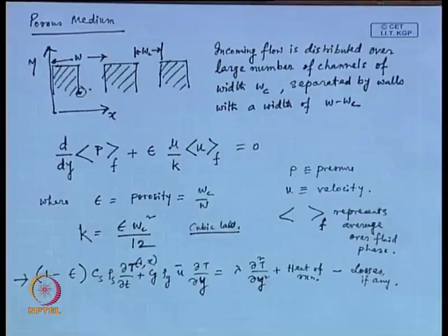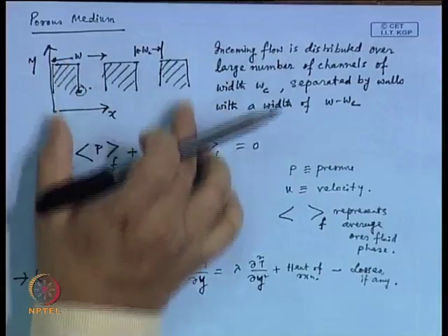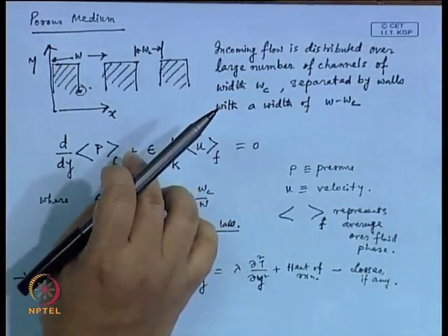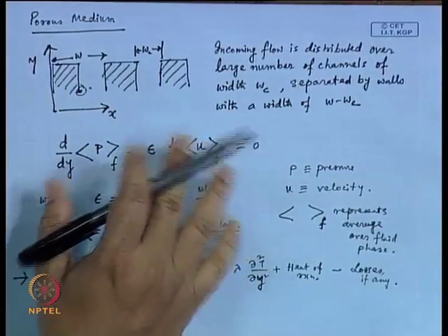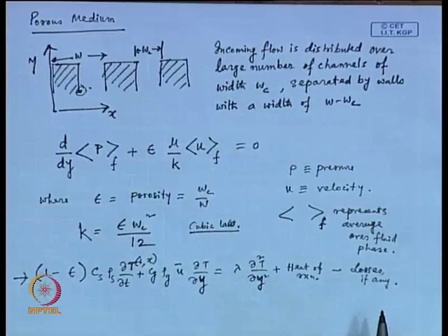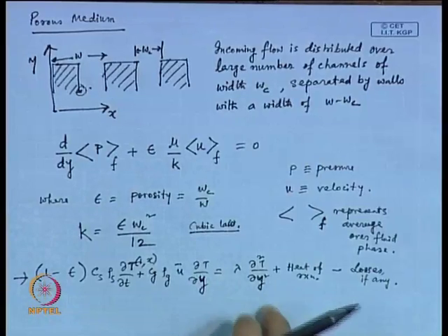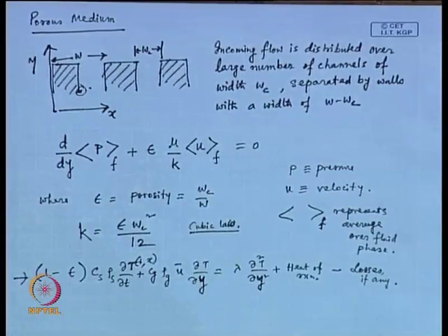So, that means fluid is flowing, say as this travels from the bottom to top. At any point the fluid and the solid temperature are considered the same. That is how this equation is to be solved. This is possible when the channel dimension is really small. This type of assumption is considered in porous medium. When the channel dimension is small and the gas is flowing through that channel, in a macroscopic sense you can consider that the gas and the solid at that point have the same temperature, they are equilibrated. Of course this is not a rigorous approach, this is an assumption.